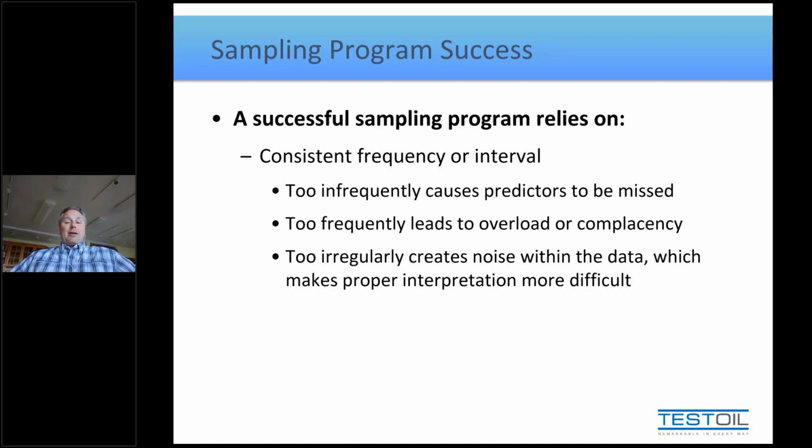Well, a lot of people try and get back on schedule. So they take the next sample when it was originally scheduled to be taken, not 90 days from the last sample. So when they take the next sample, it's taken at 60 days from the last sample to be back on the original schedule of every 90 days. So what we're comparing is 90, 90, 90, 120, and then down to 60. That really throws off the trending. It makes it difficult to see if the trend is smooth when you have inconsistent intervals like that.